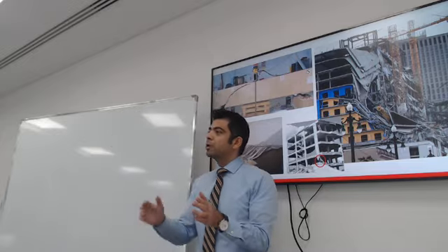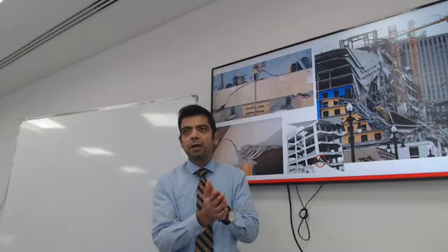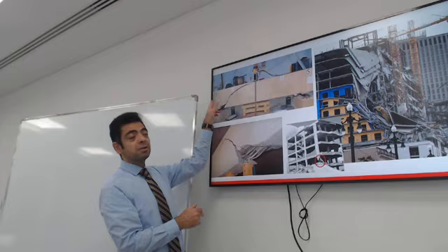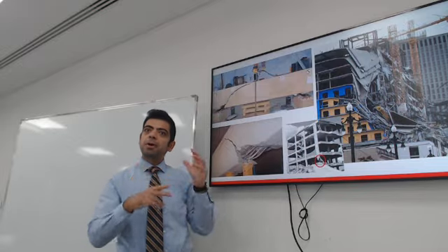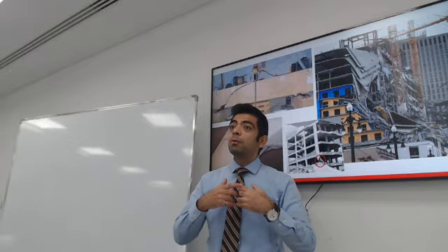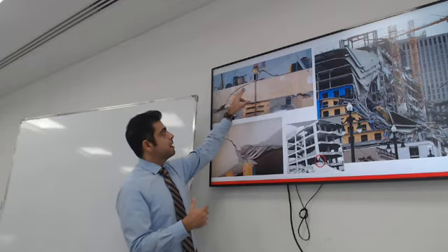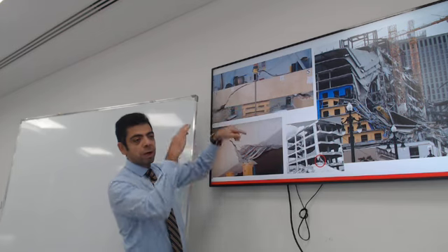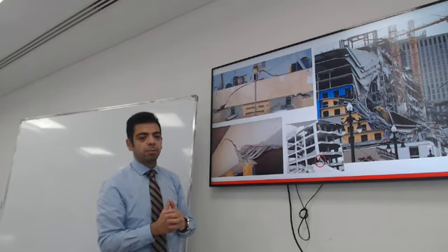It has to do with the angle of the strut of the concrete. The load is trying to work its way to the support. There is a very interesting model that simplifies this process, as if this beam has inside it a truss that is trying to triangulate and send the load safely back to the support.